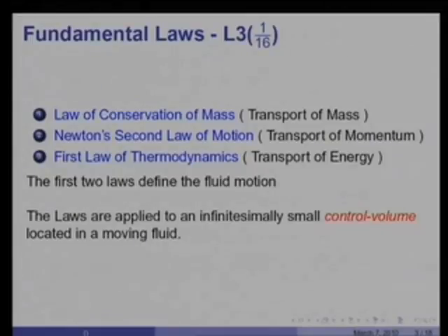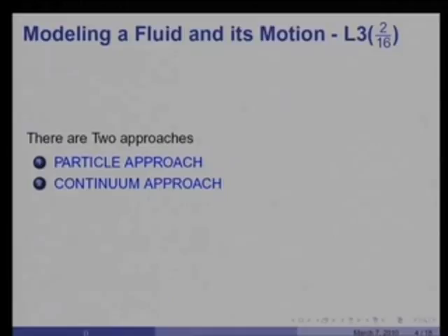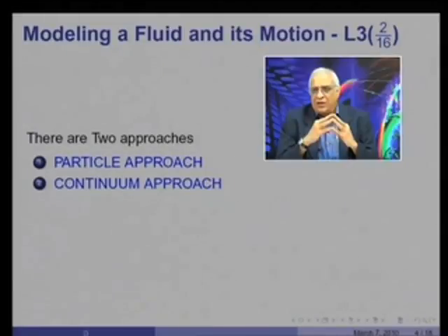So, today I am going to consider only the first two laws that define fluid motion completely, by applying these laws to an infinitesimally small control volume located in a moving fluid. The first question that arises is: how should we look at fluid and its motion? The fluid itself is viewed in two ways. The first one is called the particle approach, and the second one is called the continuum approach.